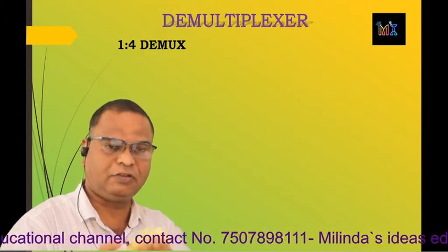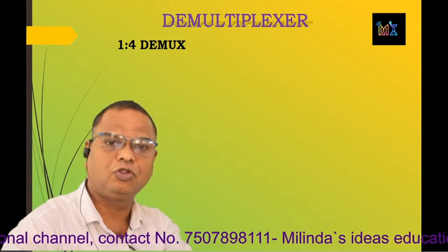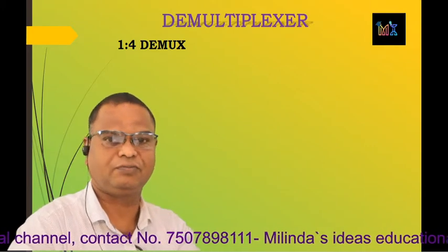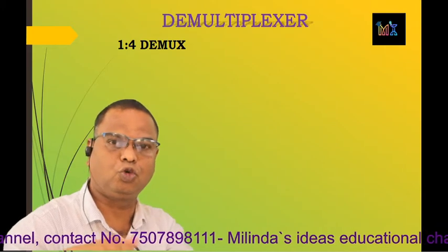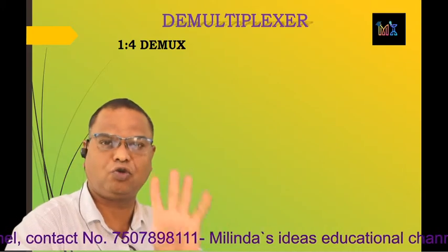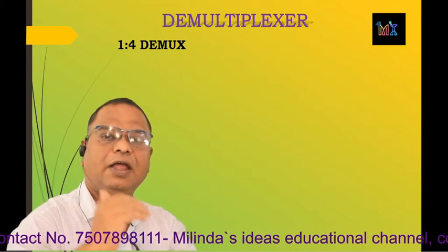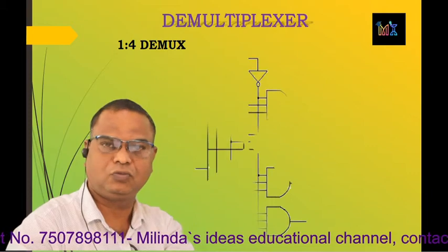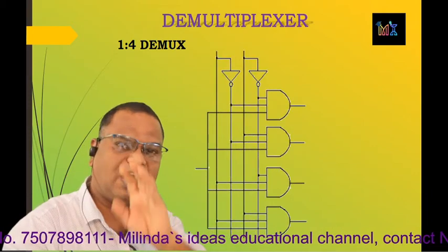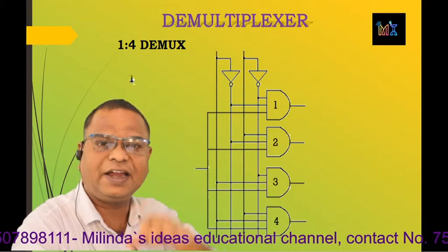So in this case, as there are 4 outputs, 2 control lines are required. 2 raised to n is equal to 4 outputs, so 2 control lines are required. And as there are 4 outputs, 4 AND gates are required. The input data, that is I or D, is common to all those AND gates.